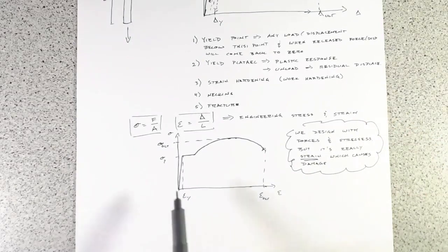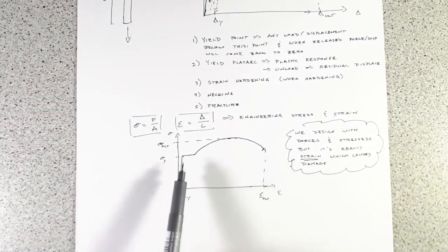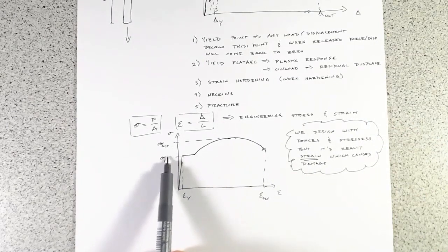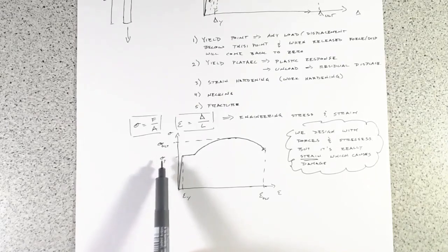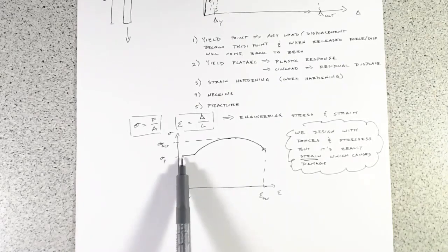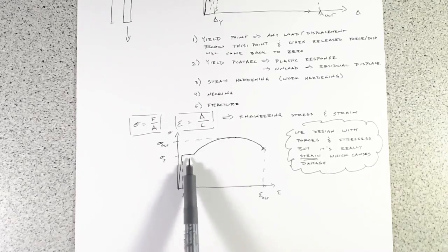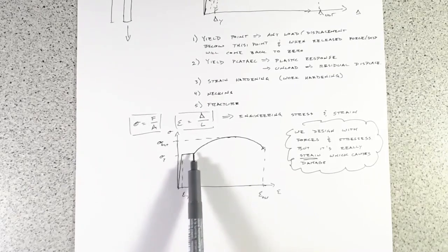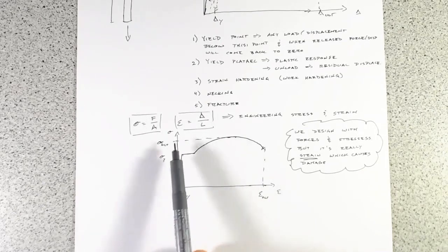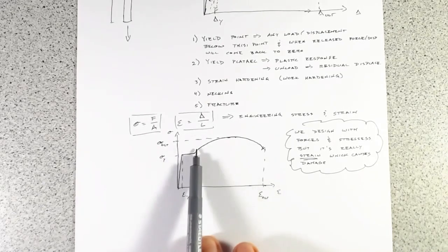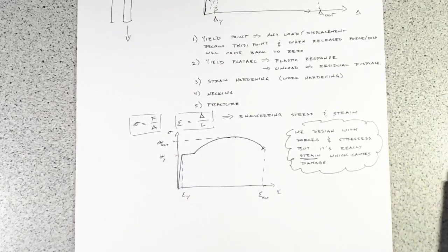And so we can look at our stress strain distribution. We can kind of see that all of our designs are staying below our yield stress. Even if we get plastic deformation, we've got a substantial amount of strain which we can go through. And even if we pull past this, we see that we don't actually go up to a much bigger force, but it's really this stretching which will end up finally breaking a specimen or a structure or a piece.